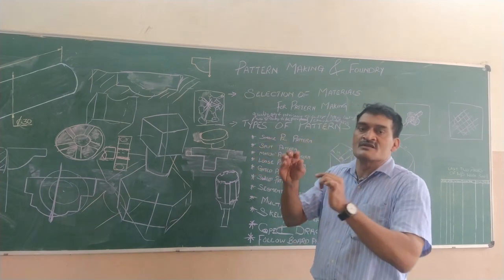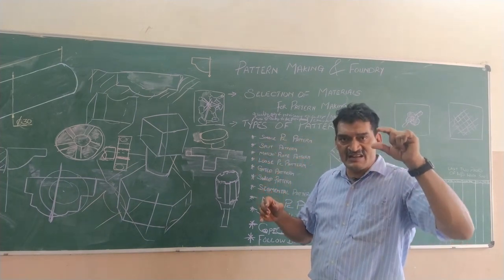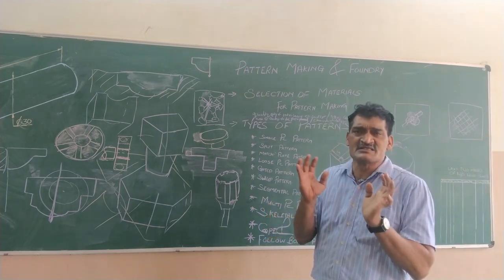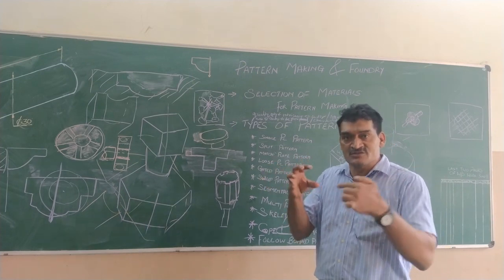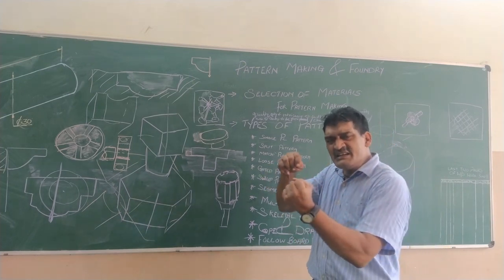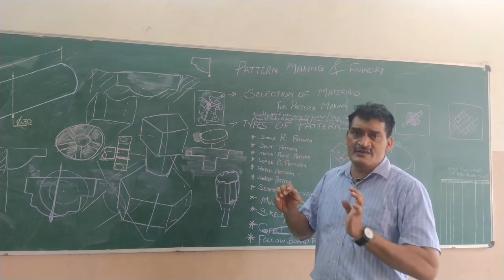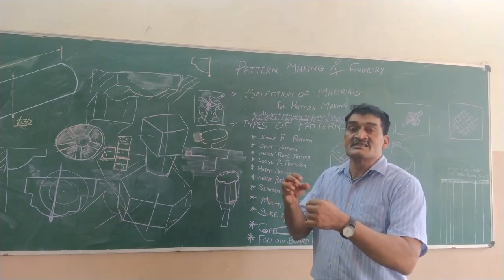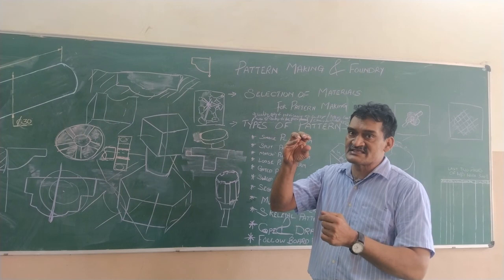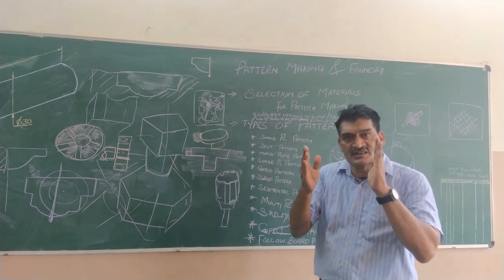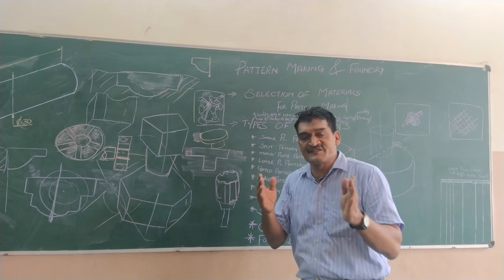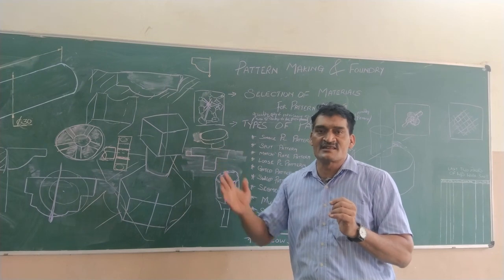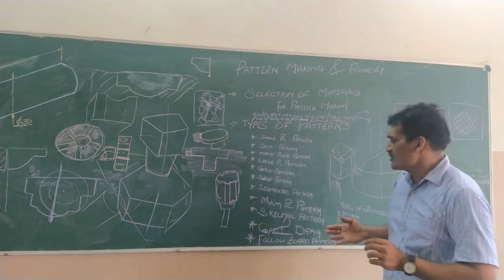In between the two, let's say your bore diameter is 25, whereas your shaft also is 25. Both are the same dimension. So it is in transition. It will go, but a slight push, a slow push will be required. Whereas in interference, the shaft diameter is slightly more. I hope you have understood the difference between the different types of fits. First is interference, second is transition, and the third is clearance fit.